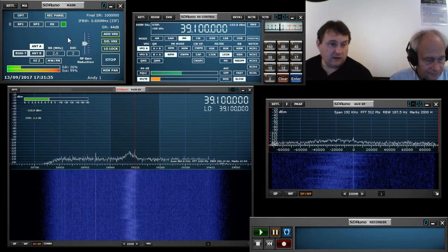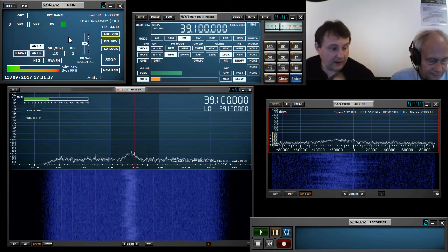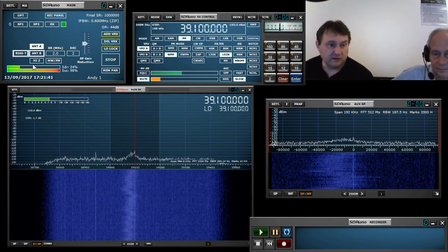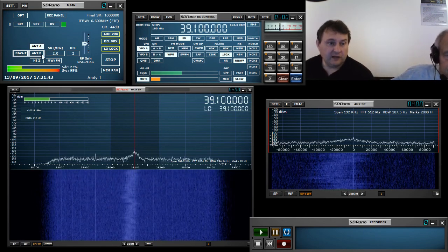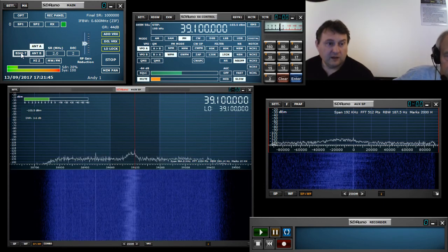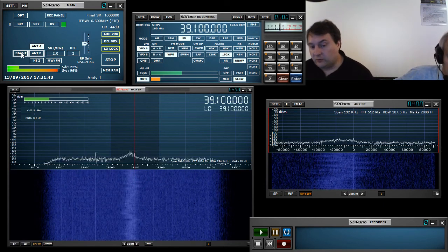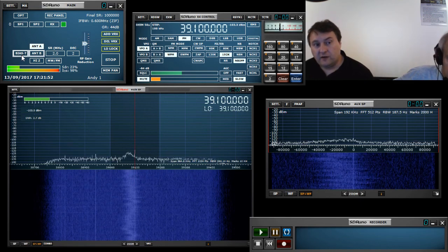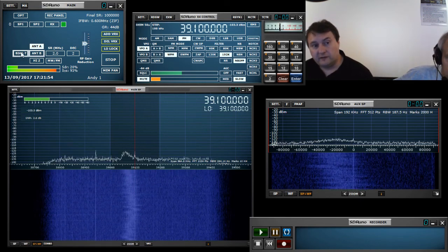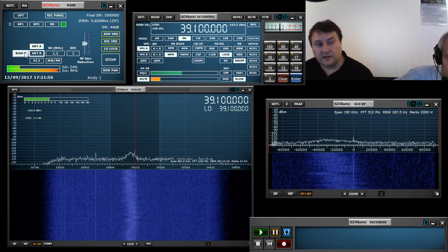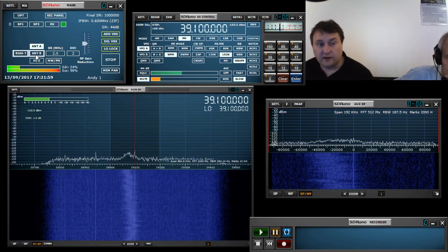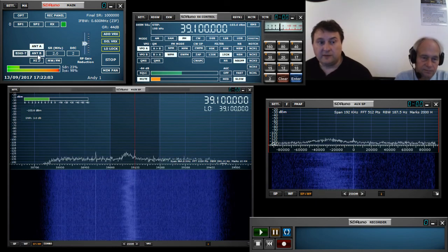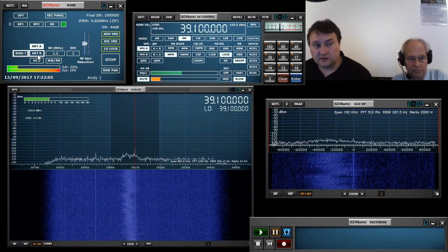Let me come back to the main window and just finish off on some of the other buttons that are in here. So we've covered the antenna port select. On the antenna B port, like I said, the one in the middle, there is a 5-volt bias T output on there. That only functions when the antenna B port is selected. So you can click on it, but nothing will happen until you actually start using the antenna B port.